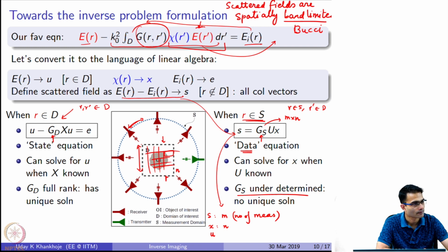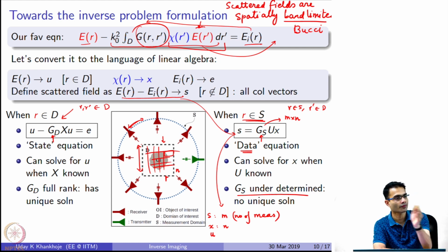But if the object size is very small, then we can add more receivers. If the object size is small, then the band limit is even smaller. So that means there is very little information. So you need very few receivers. See, the amount of information is fixed by the size of the object. So the size of the object gives you the maximum frequency, the spatial band limit, and that tells you how frequently I should sample. This is sampling in the space domain.